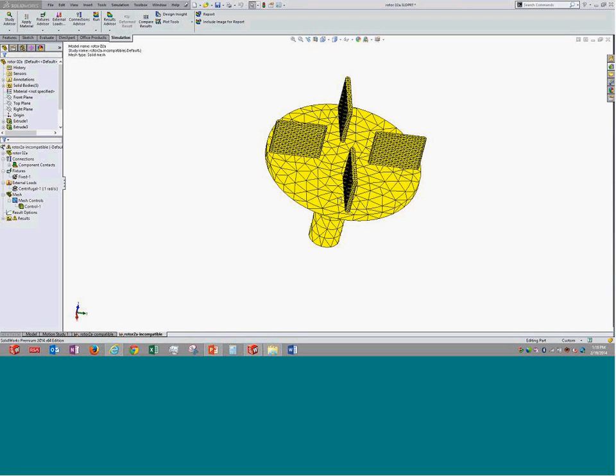Obviously, the incompatible mesh geometries are far more stiff, I would say, compared to the compatible mesh bodies, and that would be the difference. But compatible mesh is a necessity at certain locations, and incompatible mesh is for cases wherein the mesh is failing. For all models, try to get a compatible mesh. If not, then move on to incompatible mesh.